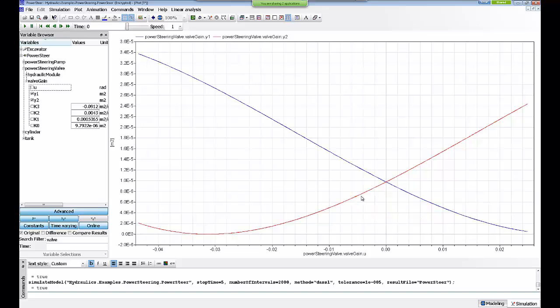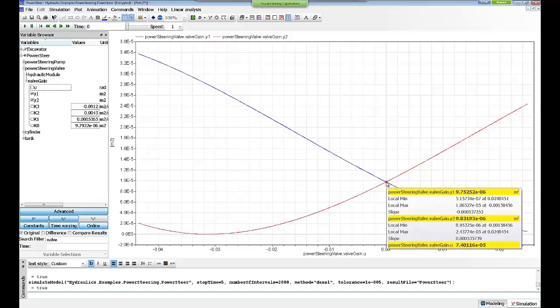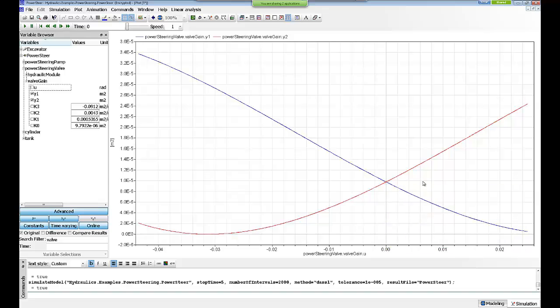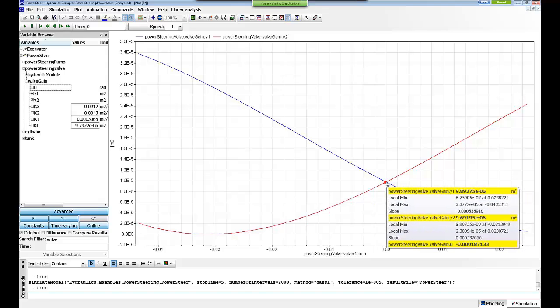And then when the deviation goes down, it stops and it's in equilibrium again. And then if we open up to the other side, we're gonna open that valve to actuate the other side instead, and then close on the other side. And then when we catch up, we're back to equilibrium. So this is a basic implementation of the booster of a power steering.